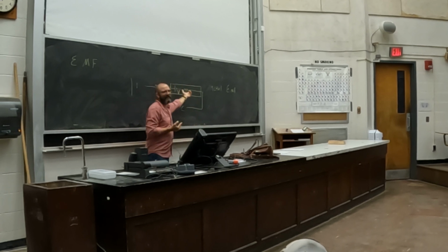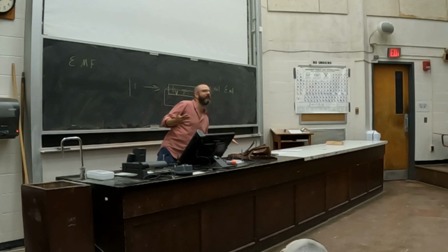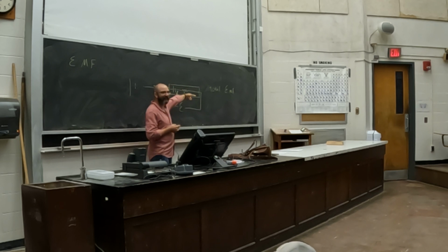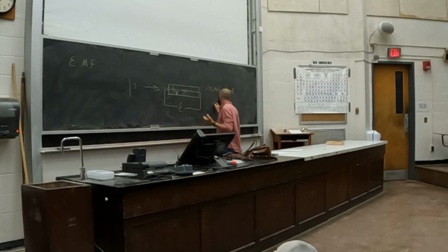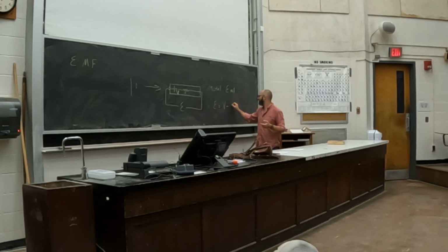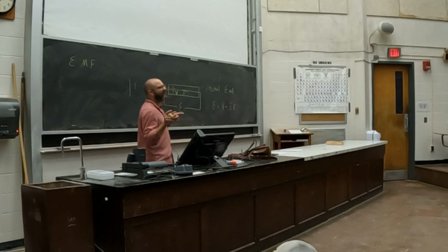Usually we don't care about what happens inside the battery. What we care about as engineers building a circuit is what the battery provides, and that's the terminal voltage, also called the EMF. But if you decide to become a battery engineer at some point, like our lab manager was for a long time, you care about this. You care about the fact that there's internal resistance here, and the chemical potential is different than the terminal voltage. So basically the EMF is going to equal this idealized internal potential minus IR, where you're going to recognize, hopefully, IR as the voltage drop across that internal resistance.